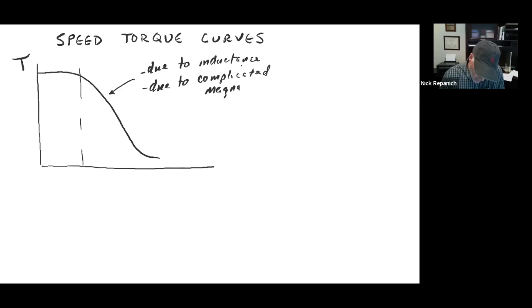And by magnetics, most of that is because it has this thing inside of it called teeth. They're machined teeth that are designed to focus that electromagnetic field. And so it has a fairly high stiffness. Physically, when you take it apart, when I get my stuff, I'll have this to show you, it has machined teeth in it that line up. And when they line up, it gives a high stiffness around that tooth. And so it holds its position really well. And it's one of the things that makes it useful.